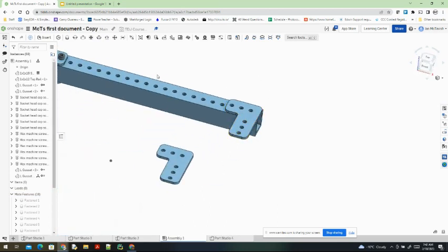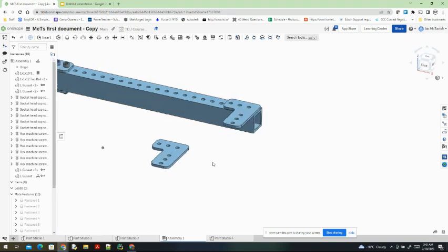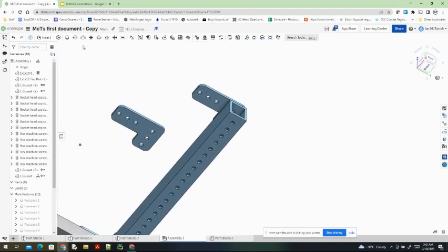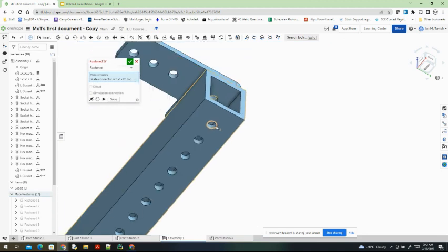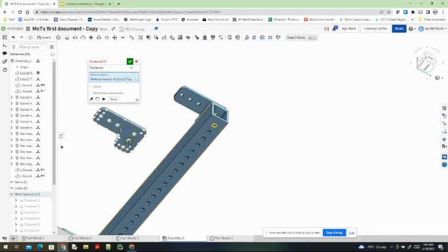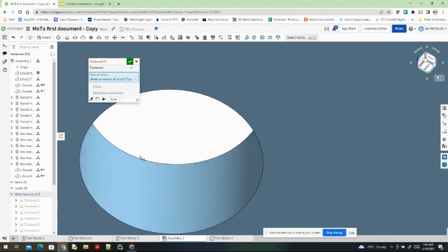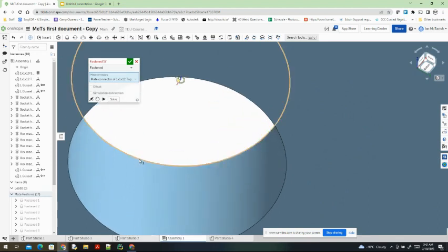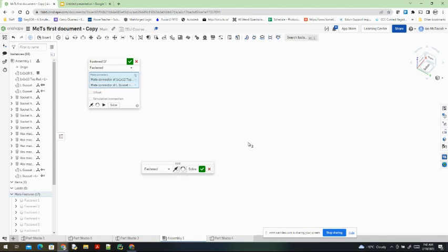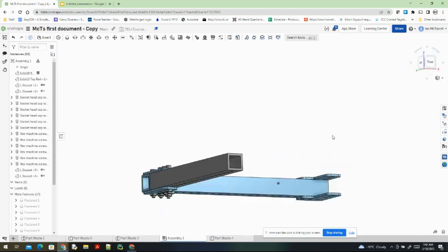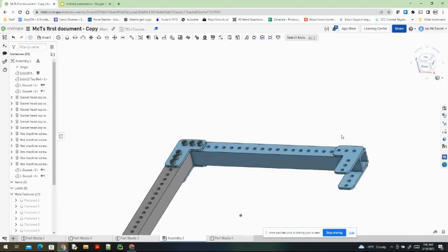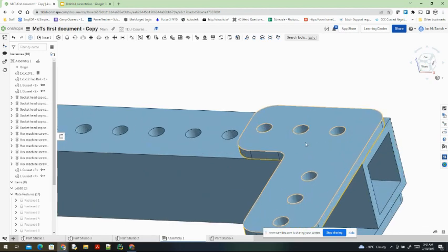And that's why I rotated them to begin with; it makes it easier to do that. So I'm going to zoom out, press M for mate connector, and zoom in to make sure that I'm getting the right spot. I look at the red, green, and blue from the mate connector, then zoom out, making sure I'm going into the right spot. That's where using your scroll wheel and practicing zooming in and out is really crucial. The first couple times you do it, it's really hard, so take the time to do it multiple times.